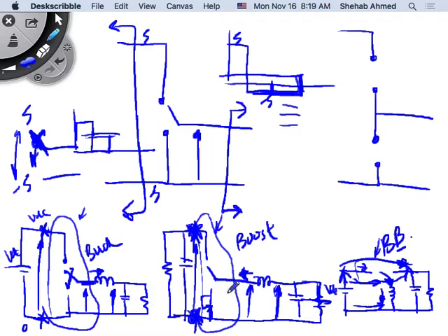This was my MOSFET. I was storing energy when I was connected to the bottom here. Right? And I was able to store more energy the longer I stayed connected to the bottom. That means I can live with a smaller voltage source to boost to the same voltage that I wanted to boost to, for example. So staying at the bottom here allowed me to store more energy, and allows me to have a high voltage here as well.